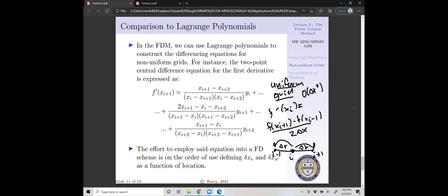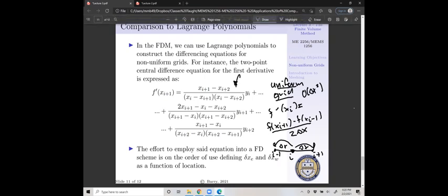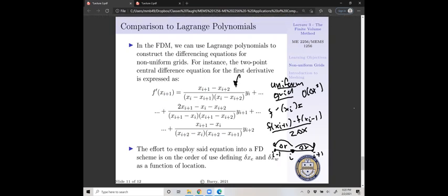For a uniform grid, here, I don't know offhand if it is second order accurate. It may be. May not. But with the finite volume method, we're really only getting first order accurate solutions for non-uniform grids. So there may be trade-offs.